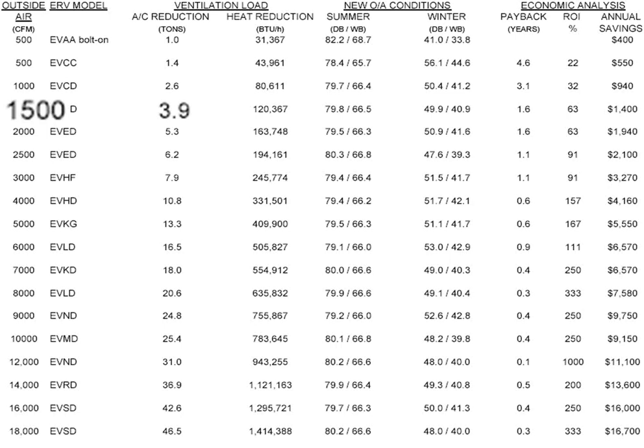Now you still got to be able to make sure you can do the CFM and static needed for your duct system, but I can get a much smaller refrigeration size of my unit. On the heating side, I was able to drop the heat exchanger size by 120,000 BTUs, so that'll typically take you out of the quote-unquote medium heat unit and down into a low heat unit.